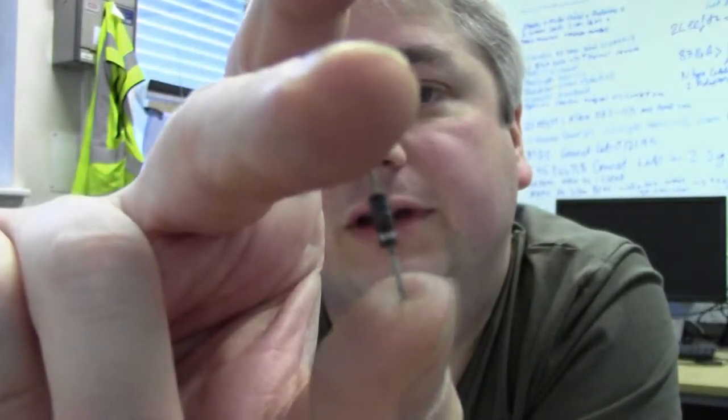Thick film resistors, wire wounds, carbon films, blue metal film ones, you've got light blue silicon wire wound ones, you've got ceramic wire wound ones. These little ones here, if we take a look, are very tubular. They look more like a little plastic rod with two wires coming out. They're your carbon compositions. Instead of a film wrapping around ceramic, whether metal film or carbon film, it's actually a plastic outing with a mixed carbon composition in the middle, for high stability. They're not really used so much nowadays because the stability of resistors has improved a great deal, but you can still buy them, they're still out there on the market.